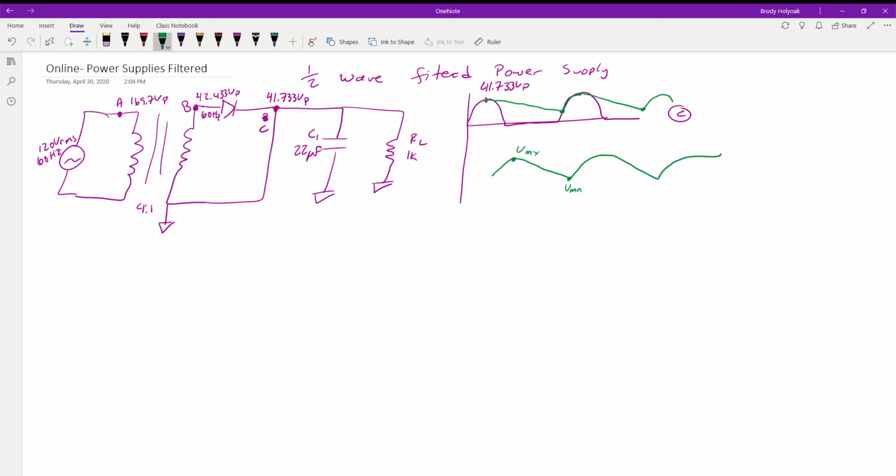So what we have to do is calculate what this voltage is at a certain period of time. We're trying to find the instantaneous voltage when it hits that time frame. How do we figure that out? If you go back and remember when we were talking about capacitors, we have this thing called tau. Remember, this is our RC time constant. This tells us how long it takes, and it takes 5 tau for the cap to fully charge. If our tau is really, really low, it's going to happen very, very fast. That's the idea we're using here.